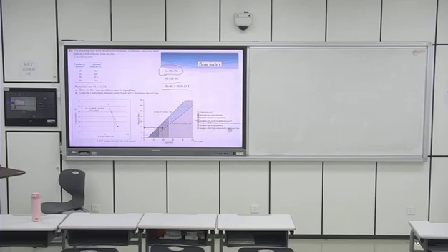Very easy. So for the flow curve, you need to know how to plot a flow curve from a percussion cup or a fall cone method, right? And then how to use the curve to determine the liquid limit, and then what the definition of plastic index is. That is the difference between liquid limit and plastic limit, right? So this is the answer of this question.